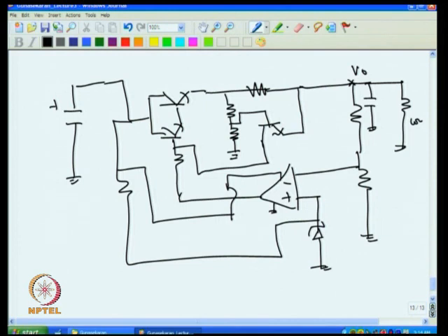Actually we had in the earlier case only this resistance and this transistor for short circuit protection. Now we added these two resistors extra and terminated the base to the midpoint of this, and once you do this, we will soon see that this circuit gives me the protection in the sense that once a short occurs, the current is limited at a lower current. In our earlier example the normal current was 0.6 ampere. Now I want to limit this to 0.3 ampere.